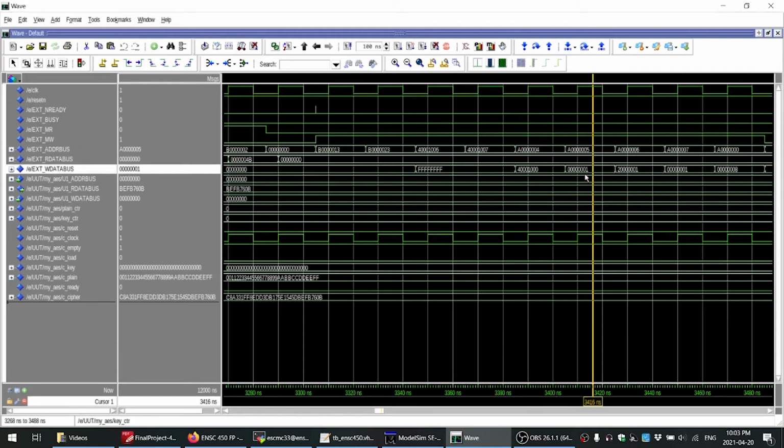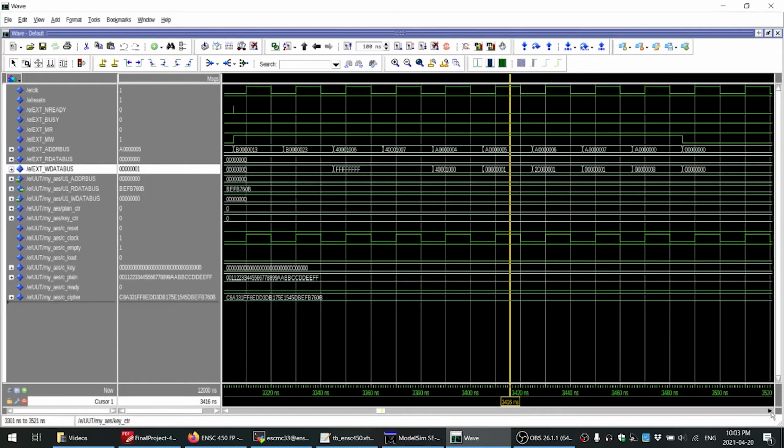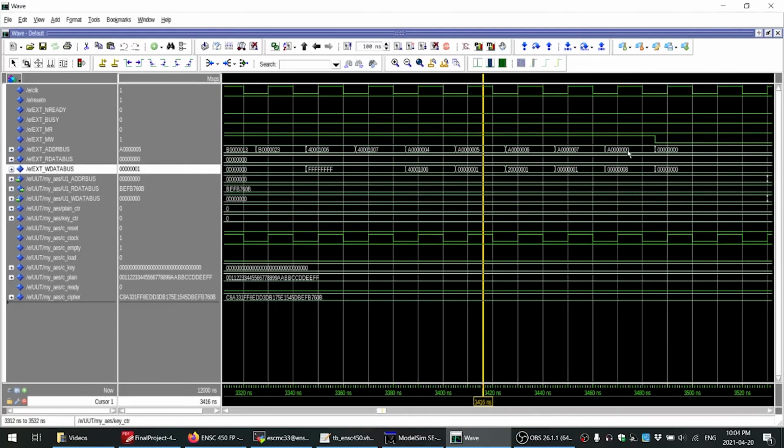And for both, the step size is 1, and the DMA will perform 8 such transfers, thus effectively transferring the 4 packets of the plain text and the 4 packets of the key.